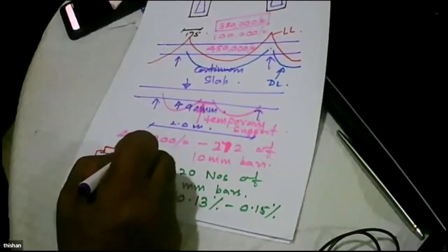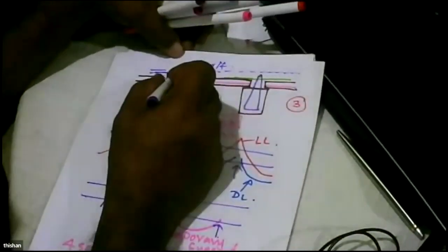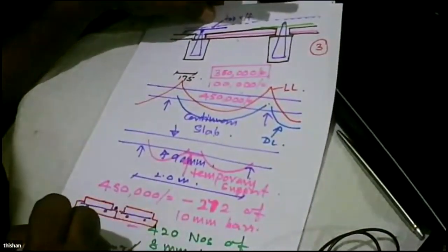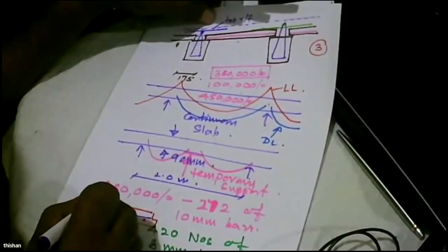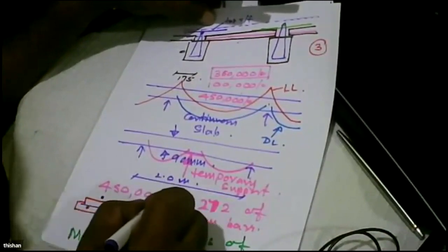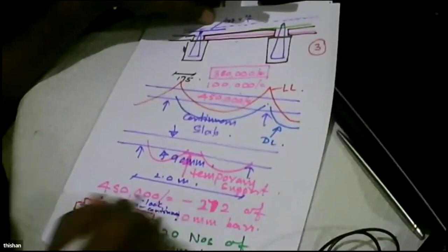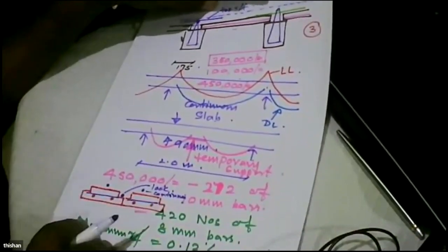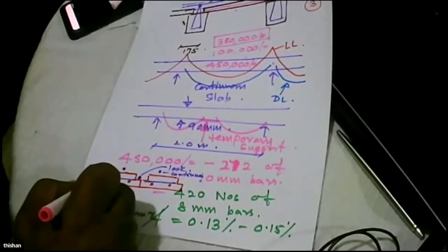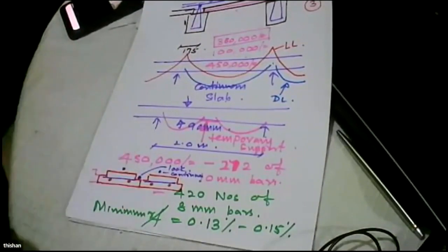And can you remember I said that we need a reinforcement for continuity? This reinforcement, the dotted line, goes there. The continuity reinforcement goes at that place. So this will lock, and this will make it continuous. And then when you are concreting, here you get another one. When you are concreting, what happens? The concrete will fill up all this area.